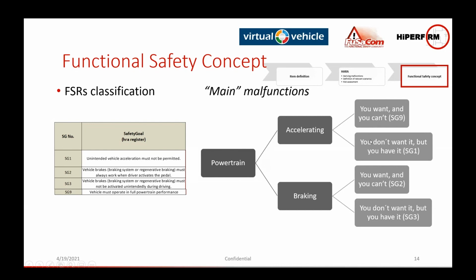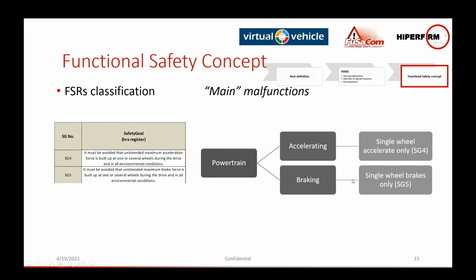Then we have a second class that is really interesting for us, that is this part of the in-wheel motor. So it's 2 independent motors, and you have to as well take into consideration that the in-wheel motor is installed inside the wheel. So if there's an issue, the possibilities to introduce safety measures are really not so high.